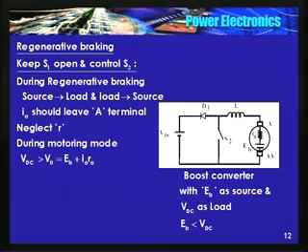Now for regenerative braking, for the motor to act like a generator, current should leave A. Okay, current should leave A. Now this becomes the source and VDC is the load. In the sense, VDC is receiving power. The source, the battery, is receiving power from the load. Okay, now I will call this the source and this the load during regenerative braking.